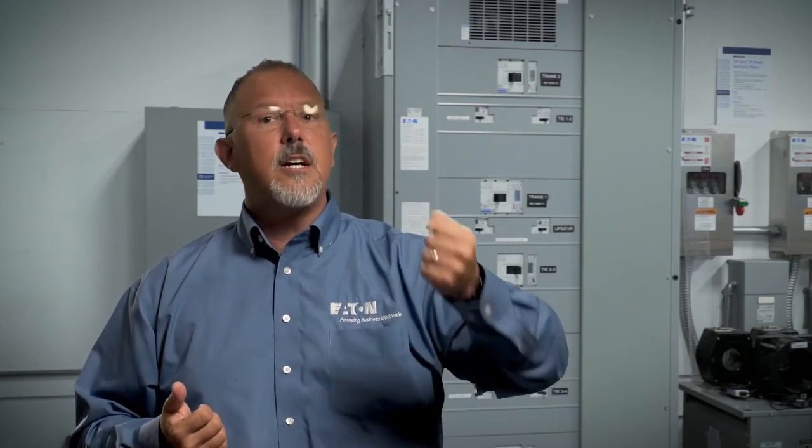All right, so everything that we've talked about so far has been about grounding and bonding of components and electrical systems. We're establishing that connection at the service or at our separately derived system between the grounded conductor and our equipment bonding and ground and earth. Now we're going to talk about system grounding, and we're going to hit solidly grounded systems versus resistance or impedance grounded systems.